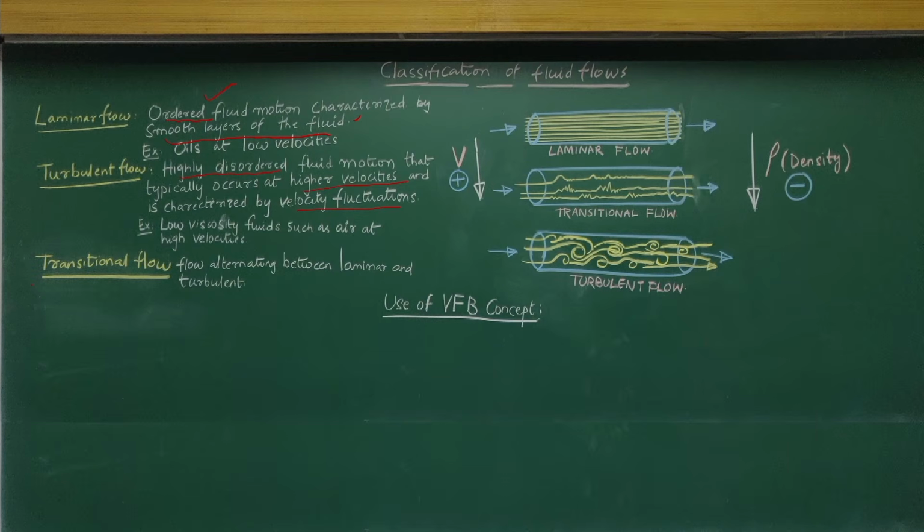Now try to understand, there will be flow where the fluid goes very orderly, layer by layer, like in this pipe flow where we have just drawn the flow paths. It shows that the flow goes in layers and follows a very systematic order from one layer to another. That flow we call laminar flow. The second flow is the turbulent flow, which is disordered. If you visualize this flow, it can have a lot of fluctuation of velocity, and there could be formation of eddies. This type of very complex flow we call turbulence. So, laminar and turbulent.